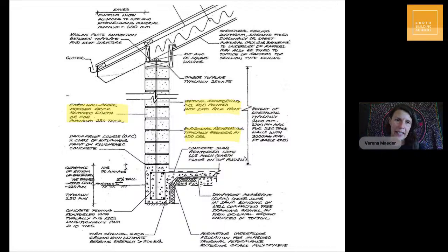And it is kind of not quite the same, but it is kind of similar in concrete construction. But in concrete construction, there's way more steel. So in your earthen walls, you typically have steel in your corners, either side of openings of windows and doors, and then every so often in a length of wall. So typically about every 1.5 meters. So not as often as in a concrete block wall, for example.